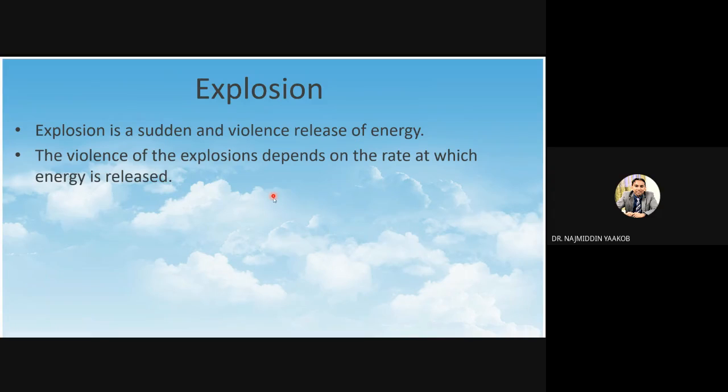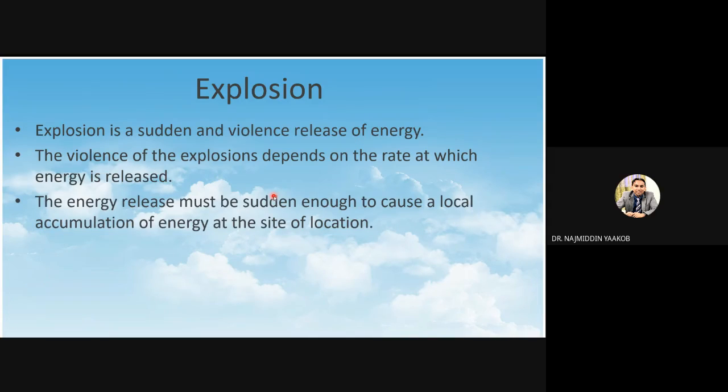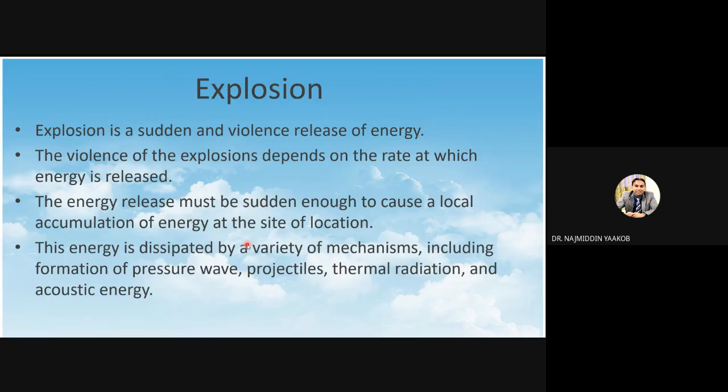Explosion is a sudden and violent release of energy. Okay, the energy release must be sudden enough to cause local accumulation of energy at the site of location. When it comes to explosion, of course, there will be a release of energy, right? So the energy then will be dissipated in various ways, including formation of pressure wave, projectiles, thermal radiation, and acoustic energy. So how is the energy being converted? This is how it's being done.